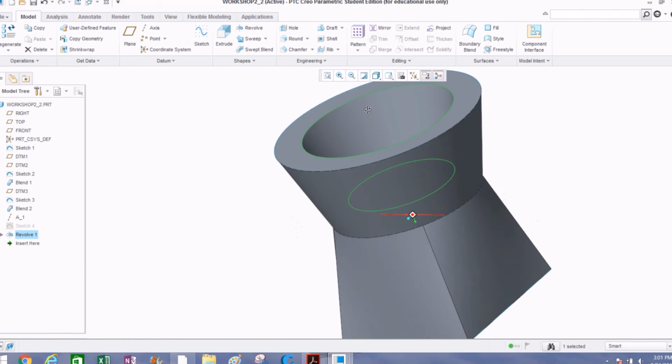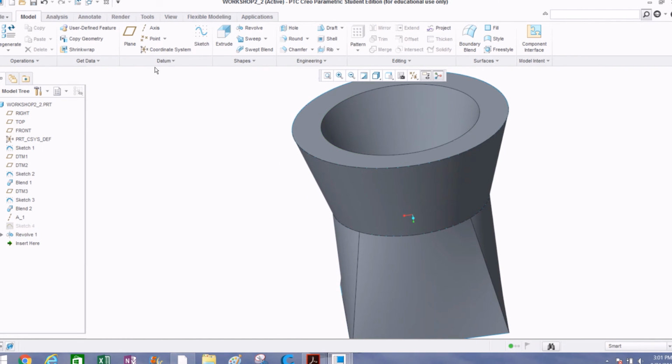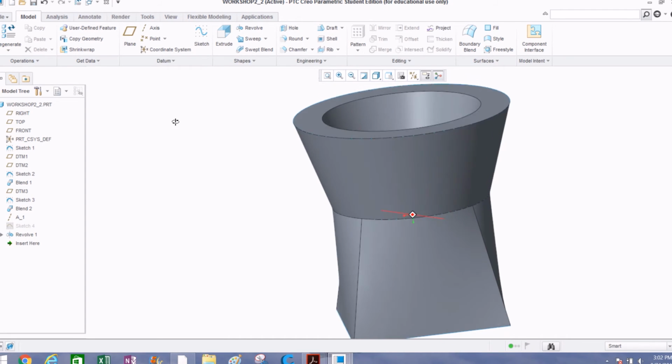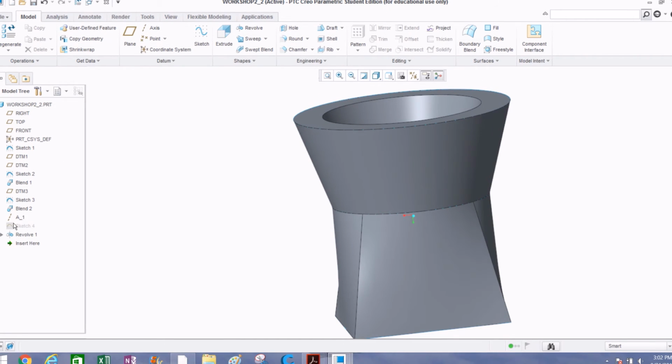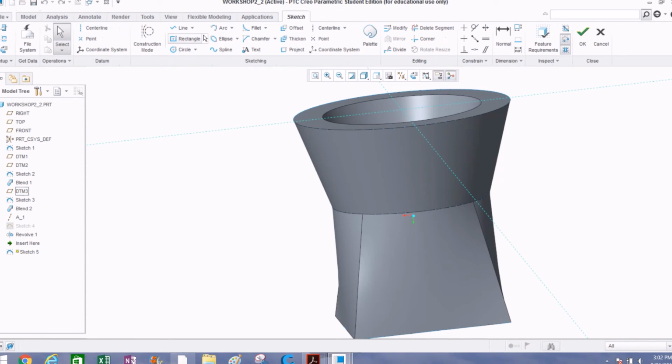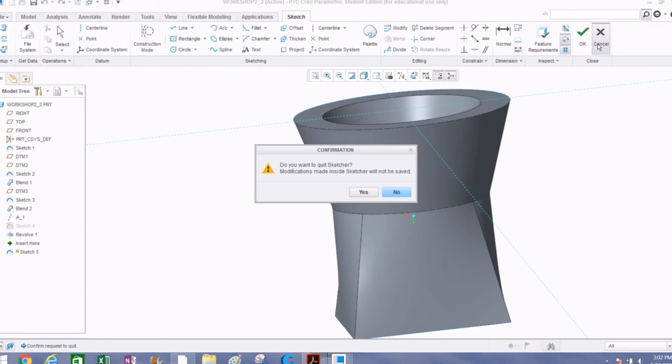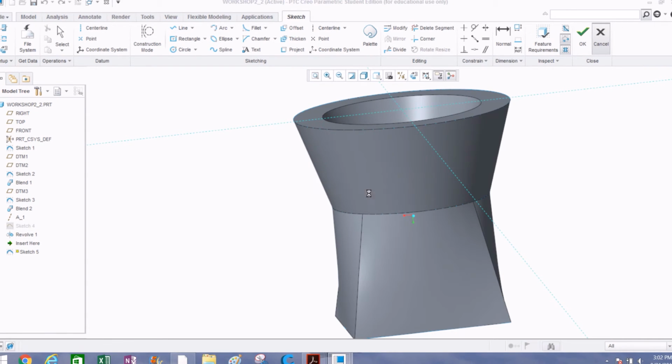There you go. There's the inside. Let's go ahead now and create the cut on the outside. Similar process. We want that original plane we worked on, so we can go ahead and select that plane. It's right there, datum 3. Click sketch. Oh, excuse me, it's the wrong plane. Sorry, X out of that. It was the wrong plane we created that from.